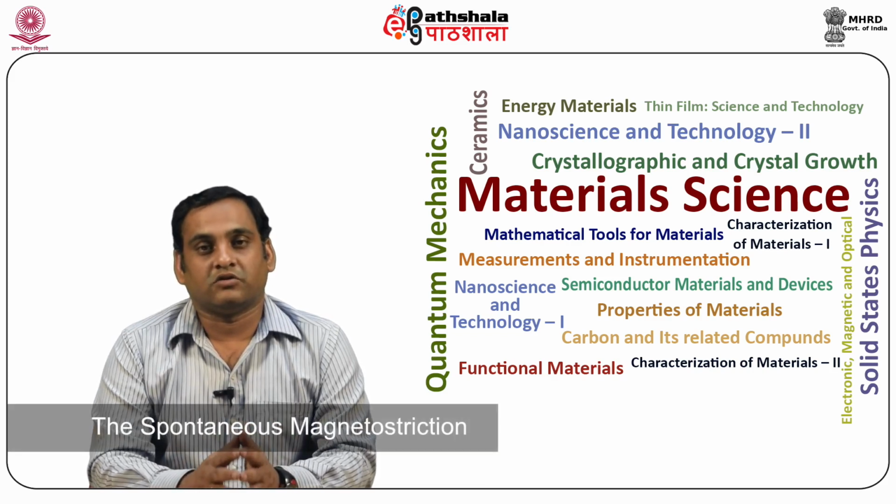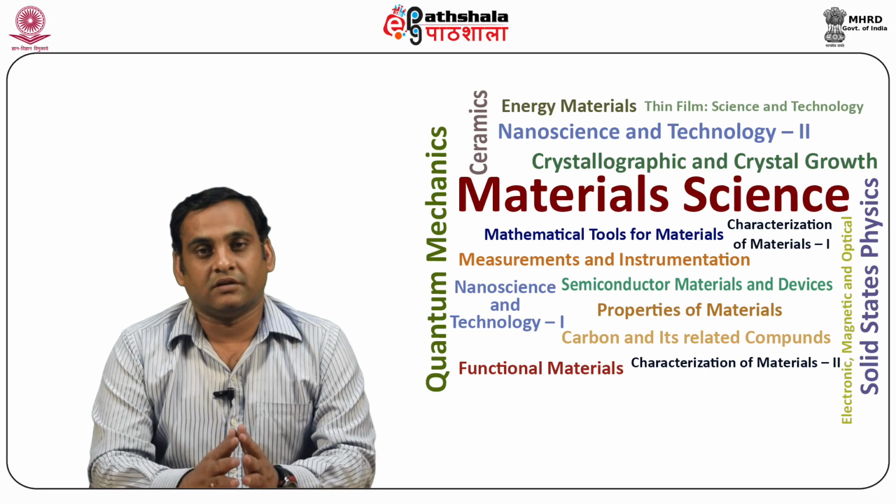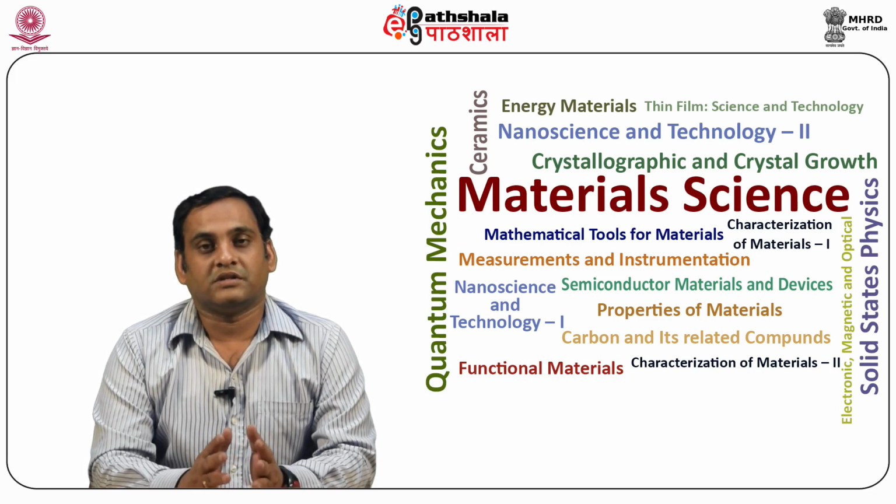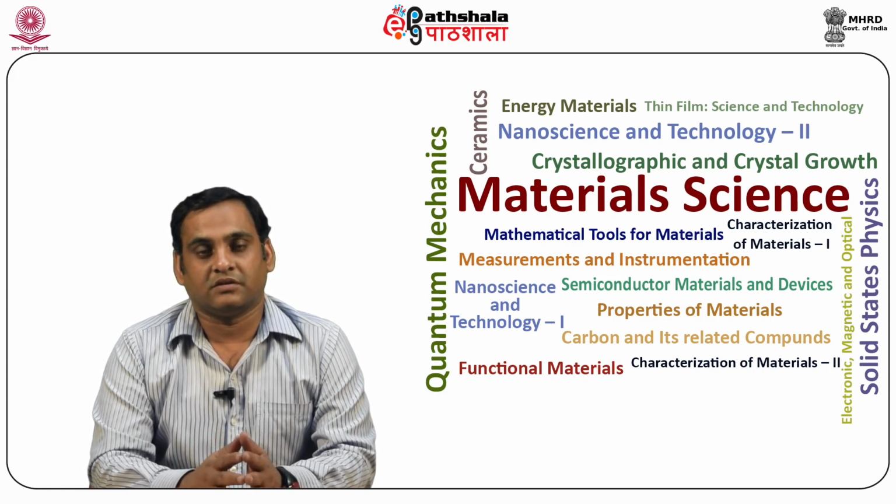The spontaneous magnetostriction is difficult to observe directly, but it is evidenced by a local maximum at Tc in the variation of the thermal expansion coefficient with temperature. This is the reason why Invar, an iron-nickel alloy containing 36% of nickel, has such a low expansion coefficient near room temperature. Its Curie point is near room temperature and its spontaneous magnetostriction varies with temperature in such a way that it almost compensates the thermal expansion.